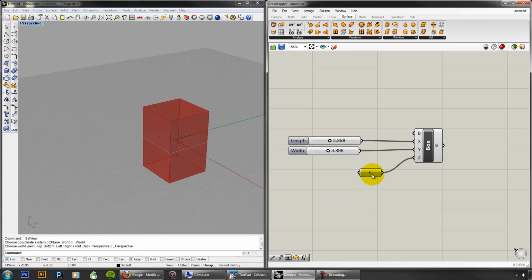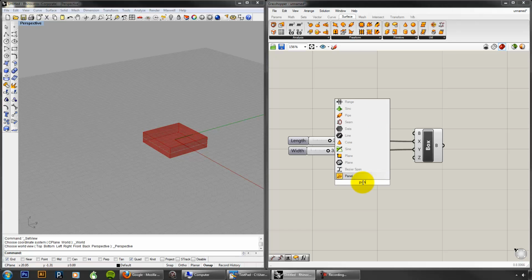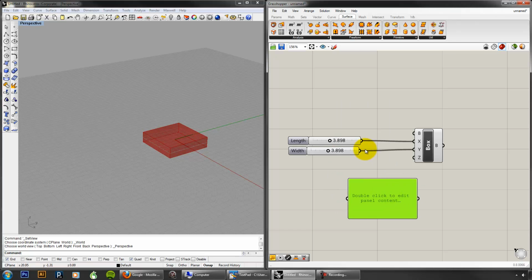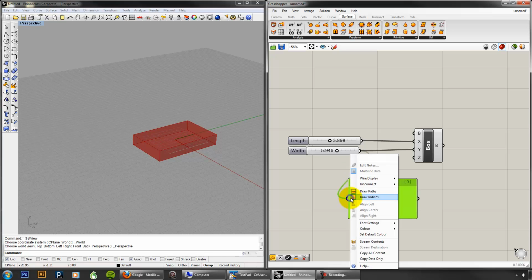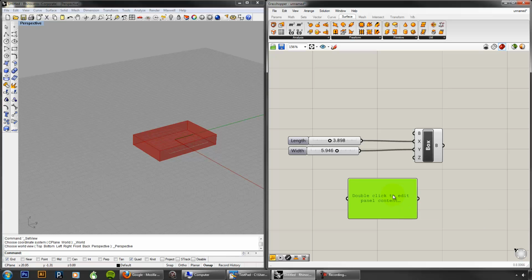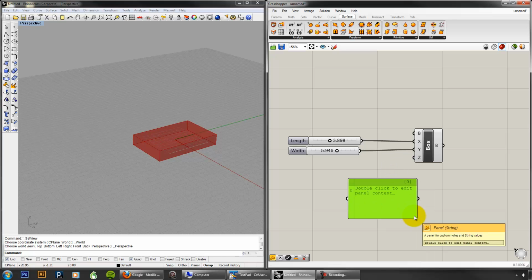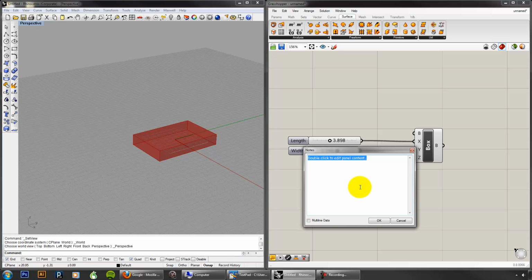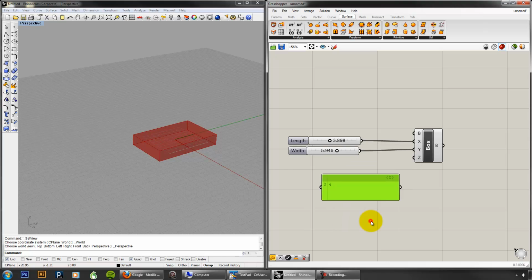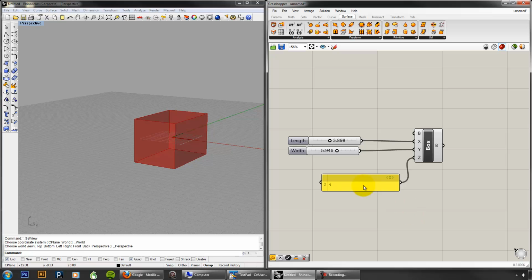Another thing you can do that might avoid that problem for you is to use a panel component as a data source. So we've used panels, and I've shown it to you, and it shows you what the value of something is. Okay, I'm going to disconnect this. You can also use a panel component to send data to something. And what I can do is right-click it, and I can say multi-line data. You have to do that, okay? And then if I double-click it, I can make this 4. And then if I plug this in for z, now it's sending data. And if I want to edit it, I can change it to 7. Okay, double click to edit. So that's kind of cool because it not only displays what's going on, but it also sends the data. So it's very useful.